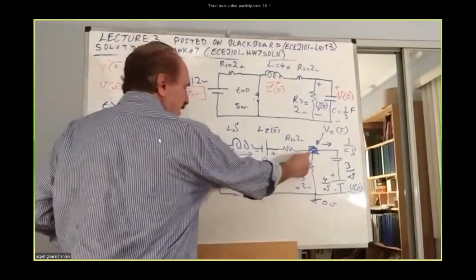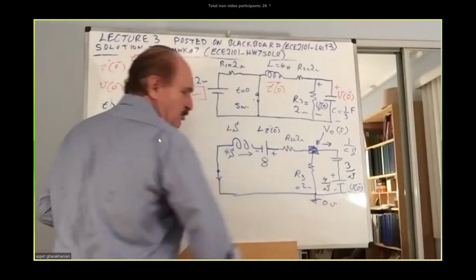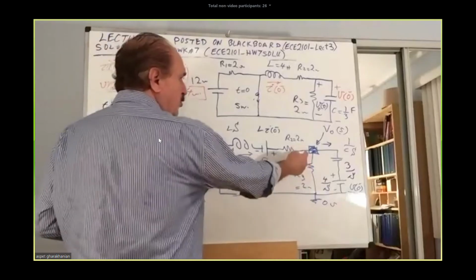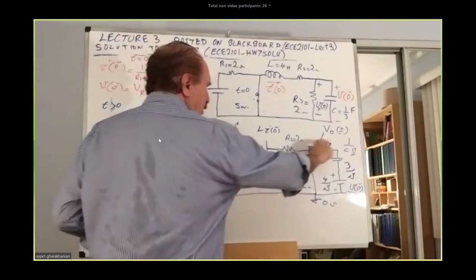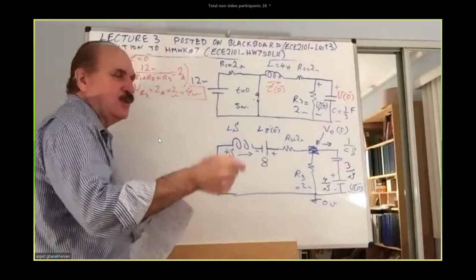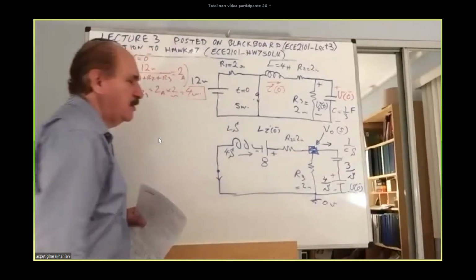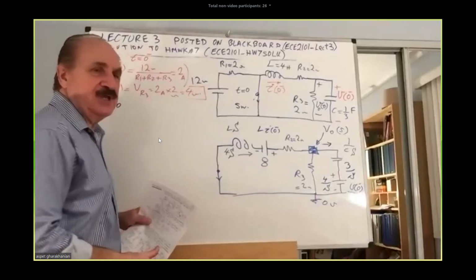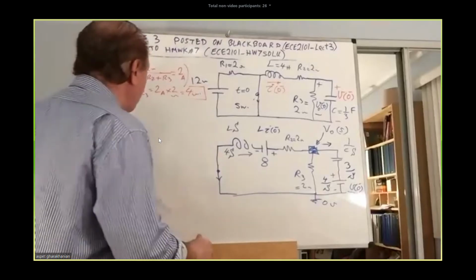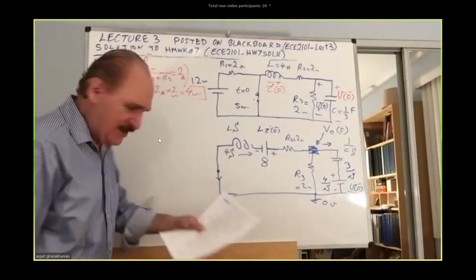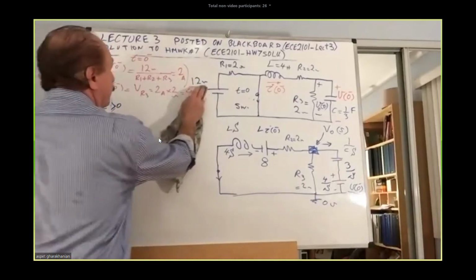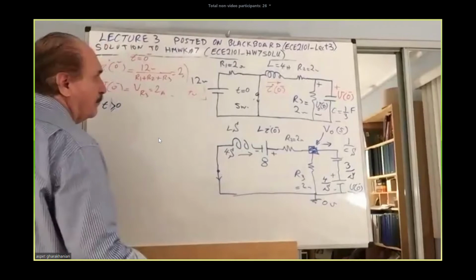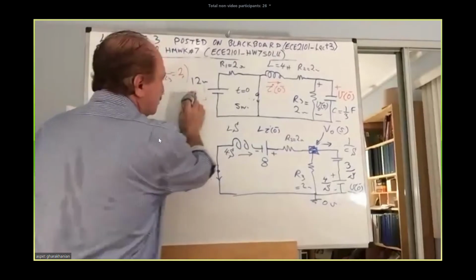So we target that node voltage. This is the ground node, 0. And we're going to write the nodal currents. Current going that way, current going this way, current going that way. That's the node equation at that point. Adding the whole thing into 0. Okay, so let me write that nodal equation. You have it right in front of you. So let me just erase the top part.